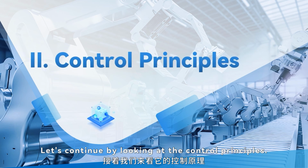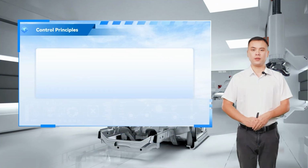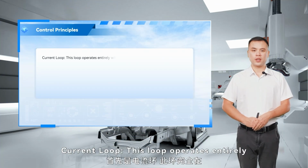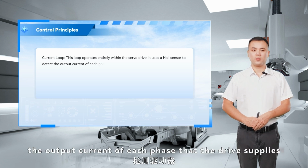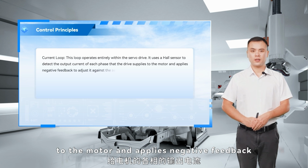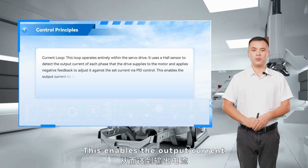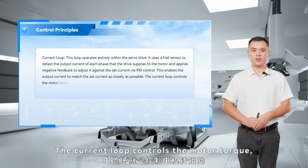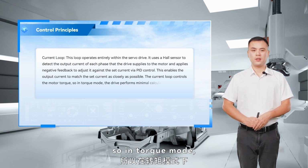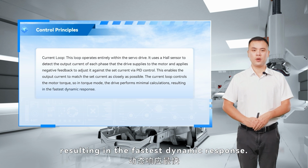Let's continue by looking at the control principles. Current loop. This loop operates entirely within the servo drive. It uses a Hall sensor to detect the output current of each phase that the drive supplies to the motor and applies negative feedback to adjust it against the set current via PID control. This enables the output current to match the set current as closely as possible. The current loop controls the motor torque. So in torque mode, the drive performs minimal calculations, resulting in the fastest dynamic response.